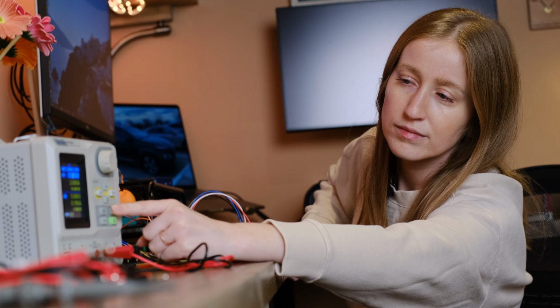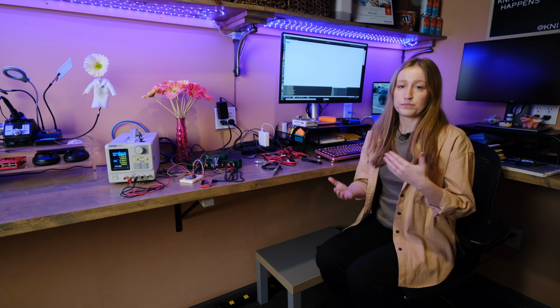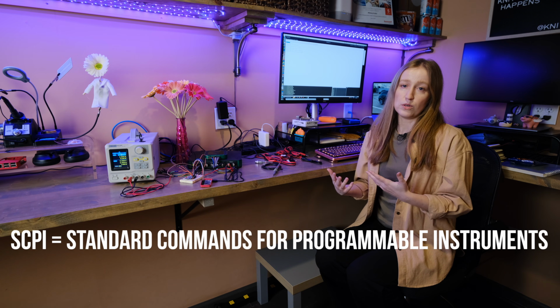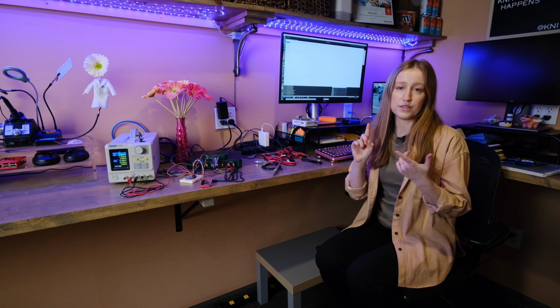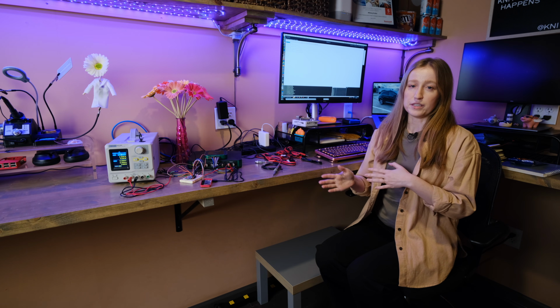And then the other option, the more traditional option that you'll run into in industry, are network controlled instruments that use a protocol called SCPI. SCPI is an acronym for Standard Commands for Programmable Instruments. It's a way to control devices such as power supplies, oscilloscopes, waveform generators, signal analyzers, all of the big fancy instruments you'll come across in industry as an electrical engineer. It's essentially just either over a serial COM port or a TCP/IP socket. You're just sending strings of commands in a certain format.